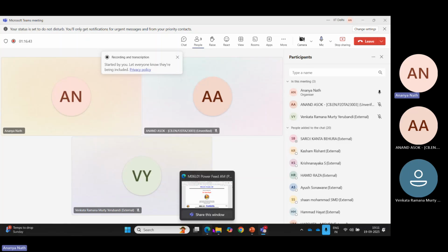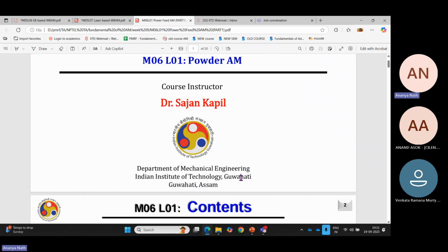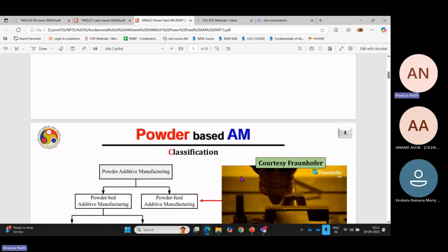When you're depositing the powder, there are some leftover powder particles. You can collect them and reuse them after sieving. But if your powder is highly prone to oxidation, like aluminium or titanium, even after sieving the powder will not be very helpful in further printing. So these are the main pros and cons.